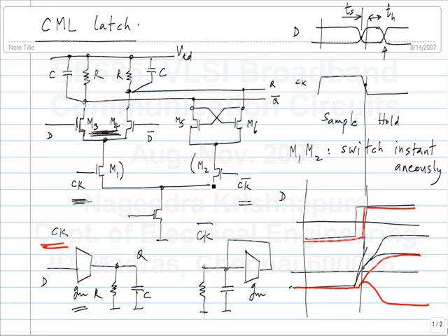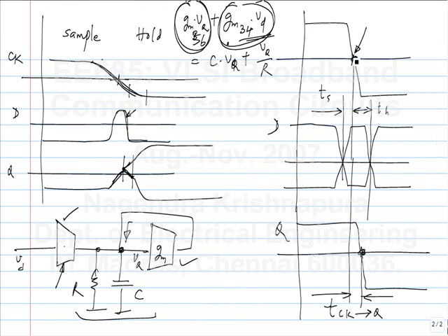So it's mainly these transistors that contribute to the clock to Q time. Yeah, that's correct. All I'm saying is, there are different measures of this, because it's not really a ramp. So I'm taking the difference between the clock crossing 0 and Q crossing 0. The Q cannot cross 0 because of regeneration. Regeneration will only take the existing polarity and blow it up to a large amplitude.